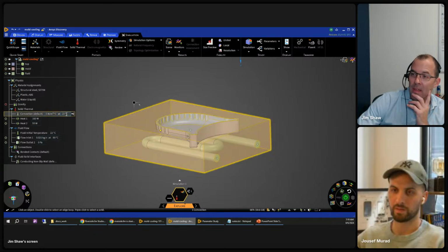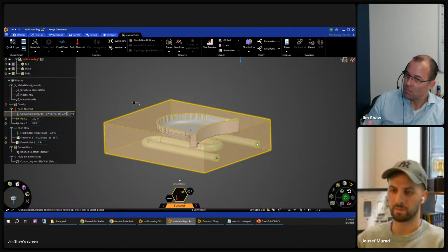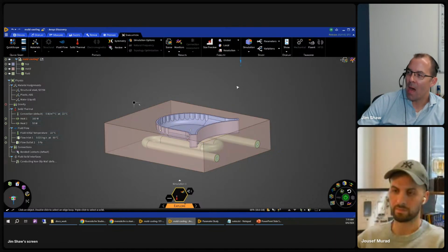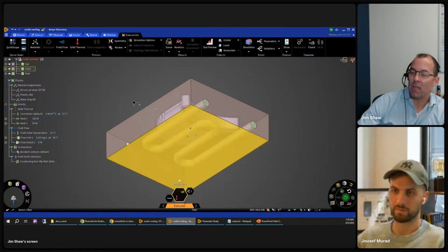And this is one thing that I think a lot of people who are new to heat transfer forget. Natural convection, unless you're in space, which can be your case, right? We're not molding in space yet. But unless you're in a vacuum in space or are operating in an environment that's the same exact temperature as your mold, which is rarely the case, you're going to lose heat to the environment. We are surrounded by a fluid, and we're not going to model the air in the molding house and the warehouse and the manufacturing floor here, but we need to account for the fact that all of these surfaces of the mold are going to be convecting and losing heat.